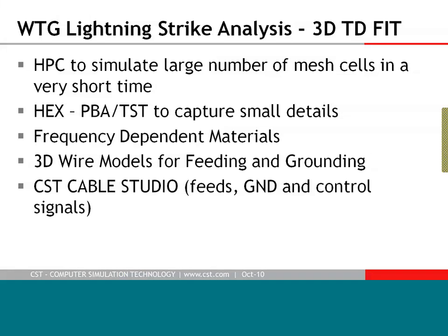And then, since we want to consider the cabling, especially signal cabling, which controls the electronic part, so I'm not talking anymore about feeds or grounding, which can be easily represented by a wire. But if you have cable bundles and so on, you might need to integrate the finite integration technique, the transient solver, with a dedicated tool for studying cables. I will show you how I applied this tool for the WTG.